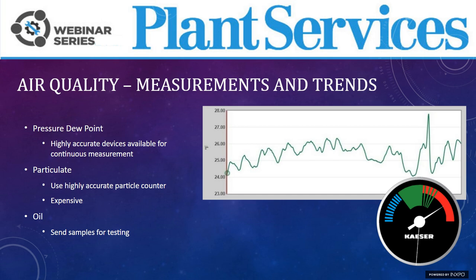Most facilities would consider pressure dew point the staple of an air quality measurement. After all, moisture in your product line could result in a plant stoppage and potentially millions of dollars worth of product scrap. Dew point monitors are readily available as off-the-shelf items and can be added to any compressor station, either to send as a 4 to 20 milliamp signal to your plant control system or via a master controller.